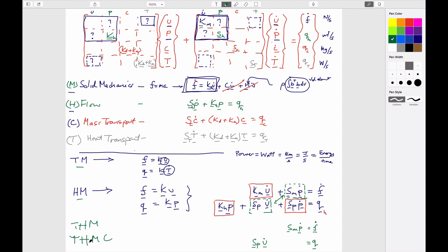And so the couplings that we're talking about, and I guess there's another useful distinction to chat about, are purely physical interaction couplings rather than changes in material properties. Both may be important, but the ones that we're talking about right here are that displacements and pore pressures are intrinsically linked because a change in fluid pressures will change displacements, and a change in displacements, if you constrain the fluids from escaping, will change fluid pressures. That's just a direct physical interaction between these.